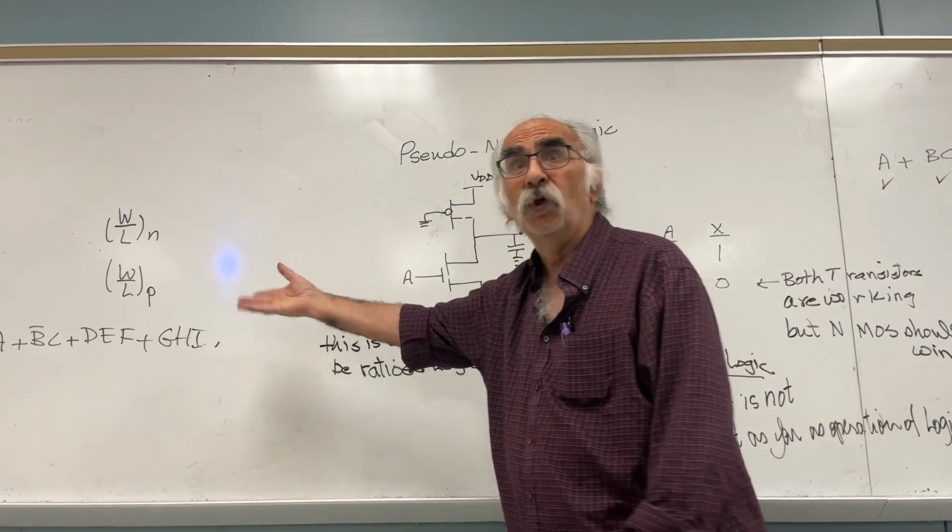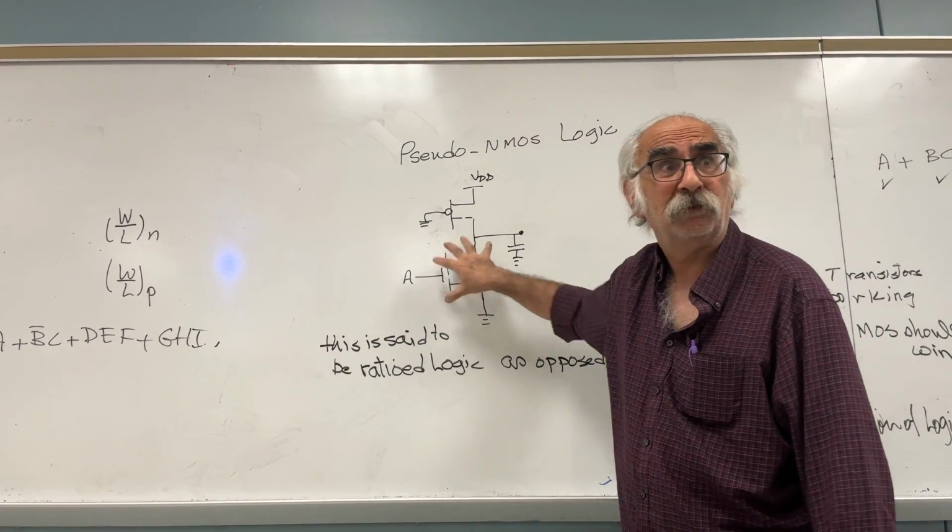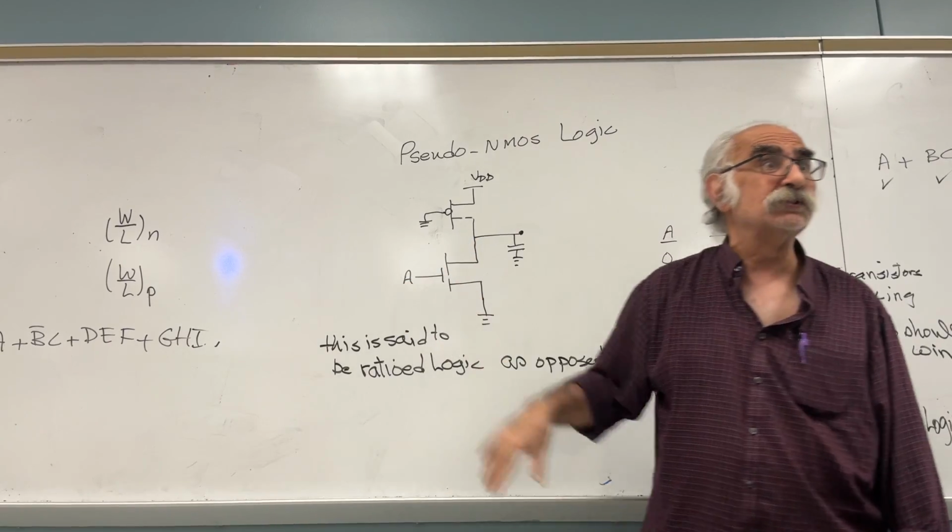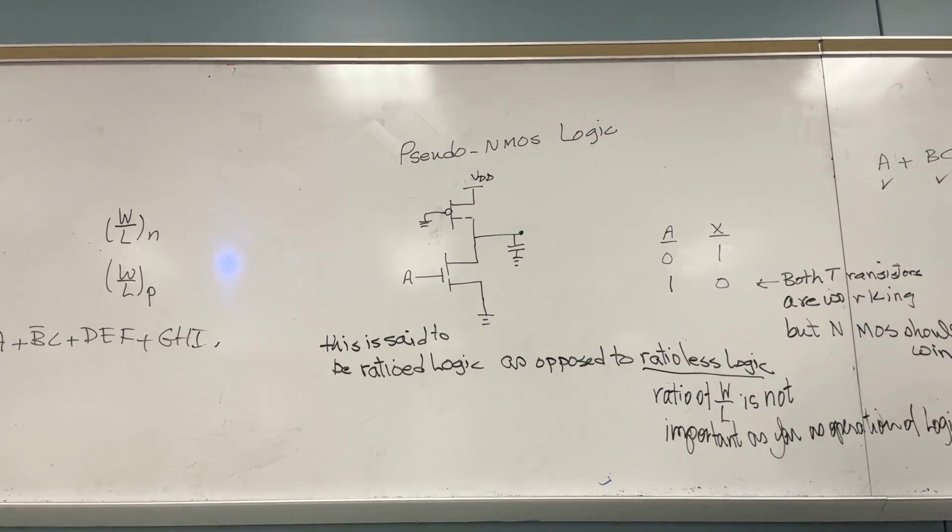The logic is implemented in the NMOS, in the PDN. Did you get it or not? And there is no evaluation or pre-charge and so on and so forth. In other words, it's not dynamic logic. Did we save from 18 to 10? Yes. We saved a lot. As the fan in becomes bigger, the saving becomes higher. Did you get it?